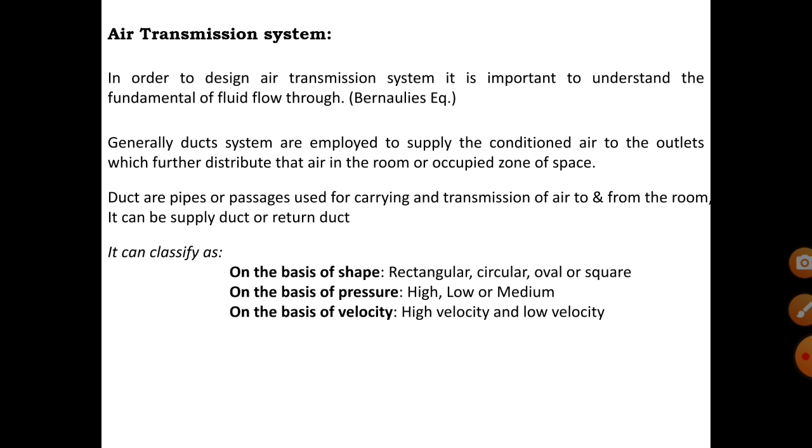And the last important thing is the cost. So the five or six things you need to consider before designing a duct are: space available, noise and vibration level, duct leakage, duct insulation, balancing of airflow in the duct, and the cost.